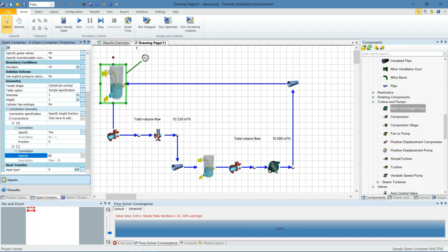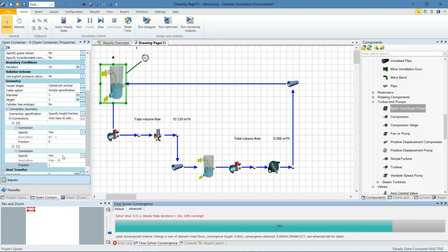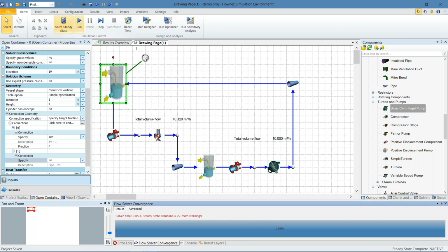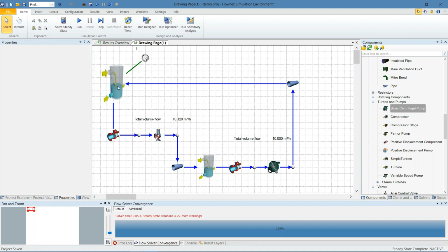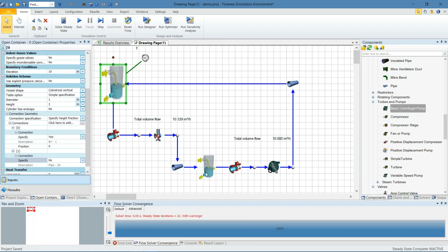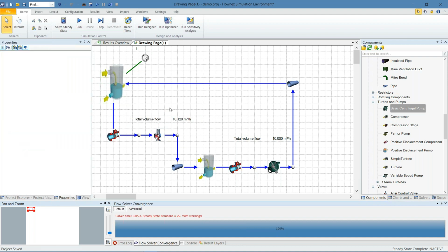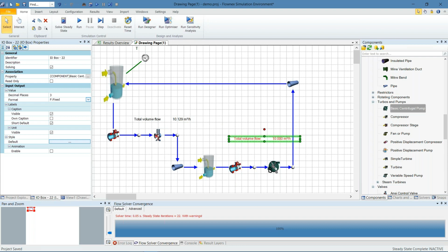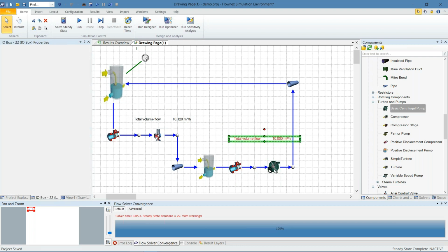If we look at this system over here, this pipe would be connected at the top. So, sorry, it's the incorrect specification. Okay, so any change in level here is going to increase the flow through here because there's an increased head of water above the outlet from this tank. So we see an increase in volume flow. Our pump itself is specified to only produce this flow rate at this pressure drop. So maybe we should design our pump to be slightly larger.